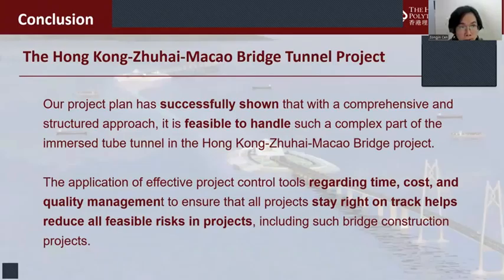By providing such a comprehensive critical path method schedule in this plan, the initial cost estimate was further improved by applying optimal analysis. The overall effect of applying measures such as mass material purchase, optimal equipment rents, and reusing resources has caused the overall project cost to come down significantly as per the client's financial constraint.